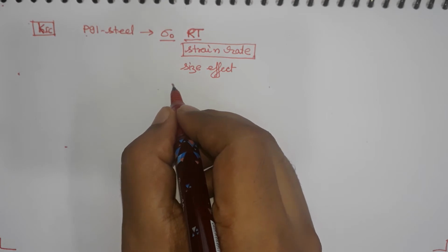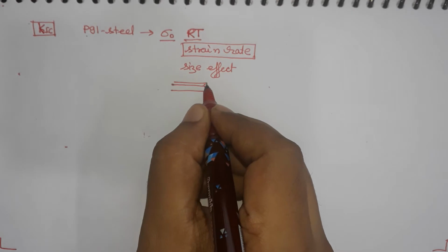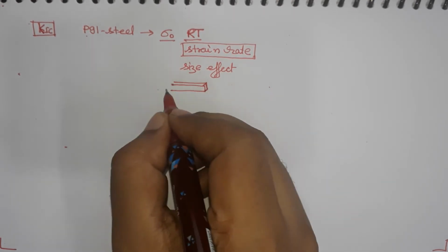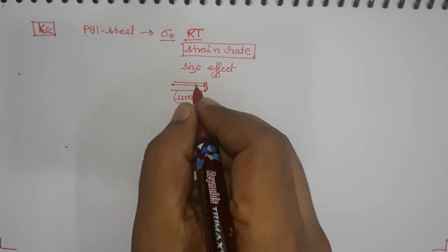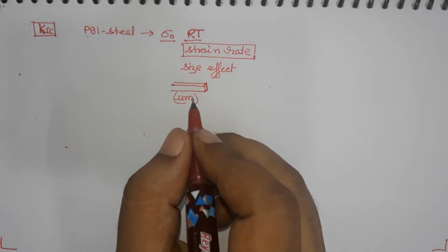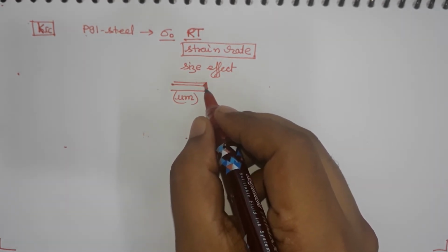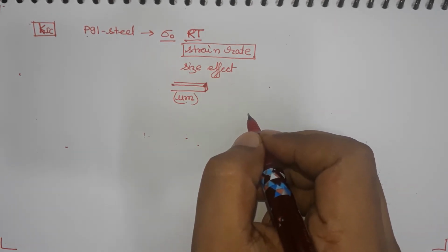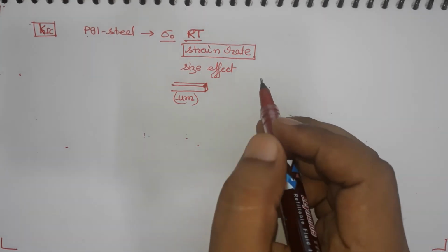So, you make a cantilever type of a specimen of graphite in the electron microscope, and this specimen is in the micrometer size. The size of this specimen is very small. So, if from this specimen you find out any material property, that could be different from what you get from a bulk specimen, in the millimeter range or bigger than that.